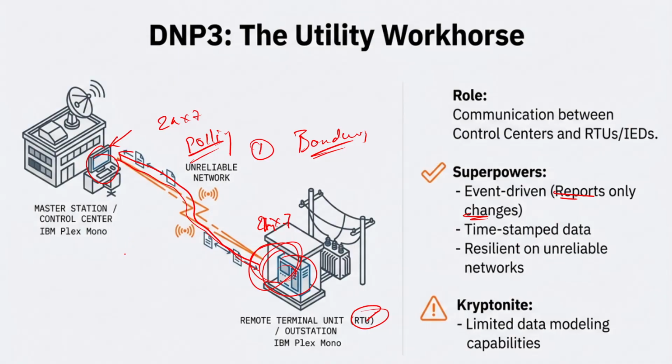And we also have another concept called SOE, that is the Sequence of Events. Basically it will keep a database of the sequence of events, right? If a fault happens, or the device is not performing as expected, these changes in the field devices will be recorded in the station, and this is called an SOE, and this will be used for analysis purposes, right?